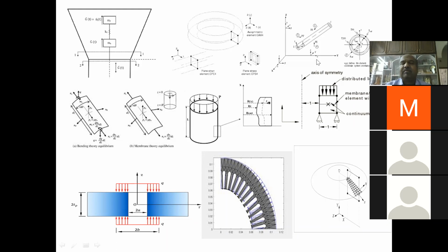That's the scenario. If you see here, one of the models has symmetry about the vertical axis, so we can cut off a section and analyze this. And here, for a ring-like member, we can take only the plane section. The plane is shown here. So for analysis, instead of the total 3D solid, we can do only the 2D plane alone, and that plane alone is shown here in two dimensions.